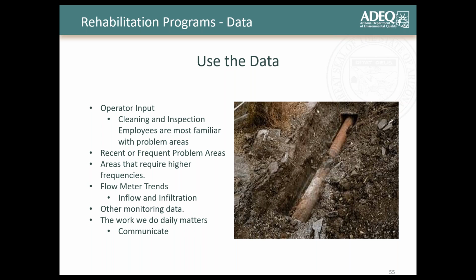The guys that are out there cleaning and inspecting are the most familiar with the problem areas and can help you prioritize. Like, hey man, we're spending so much time in this section. If we repaired this, I mean, we can go move on to different areas, right? You have to use that information of recent or frequent problem areas, right? Use the flow meter trending, right? This can help you determine, of course, your inflow and infiltration, right? Other monitoring data, like those manhole monitoring software pieces of equipment that we talked about.